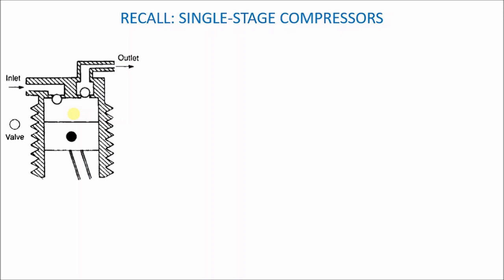And so what happens when compression is taking place? One, the pressure is going to increase. Two, the temperature is also going to increase. And finally, also the volume is not going to increase, but rather decrease, because it is compression. If you compress something, you cause its size to reduce. And so both valves are closed. As the piston is moving up, the air inside of the cylinder is now beginning to be compressed. So its pressure is rising, its temperature is rising, but its volume is decreasing.